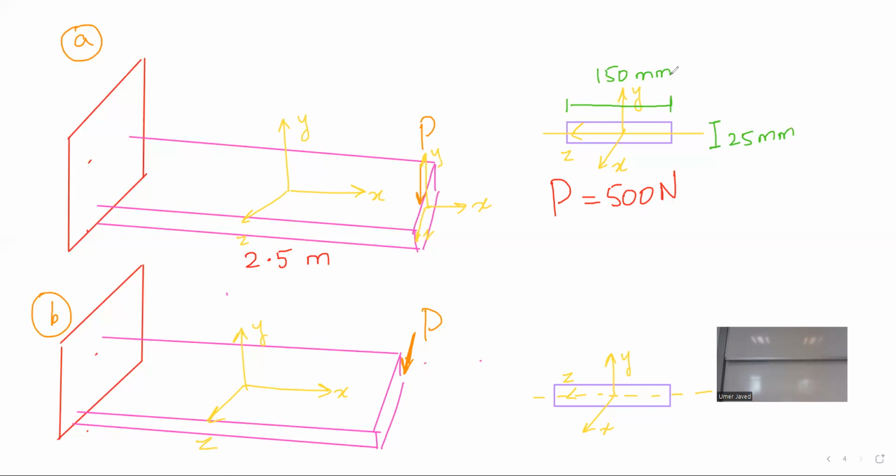When you are talking about maximum tensile and maximum compressive stresses, you have to find the maximum moment first using statics principles, in which your professors used to teach you how to make a bending moment diagram. And in that bending moment diagram, you used to have a maximum moment. You find that one and then you proceed.